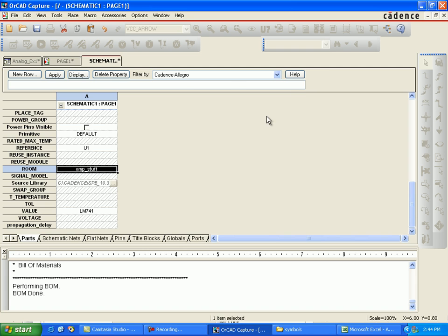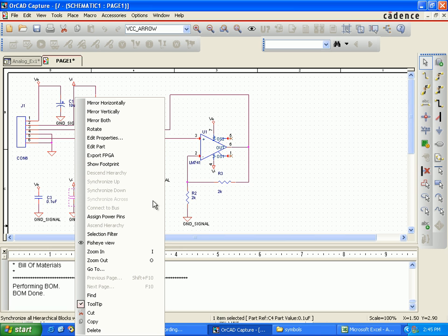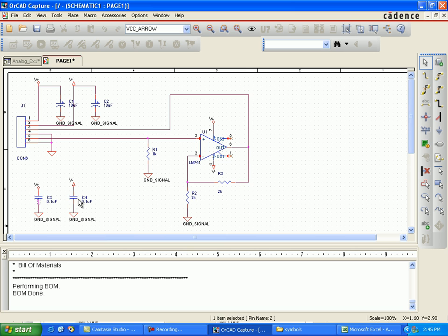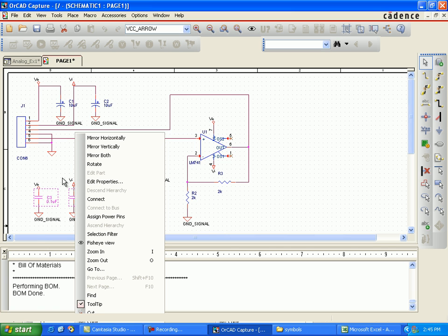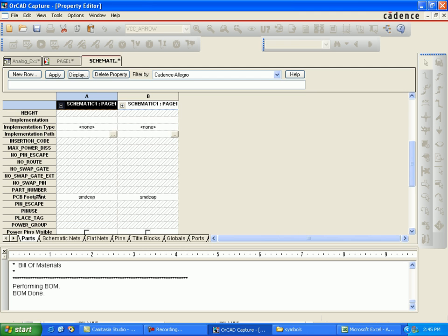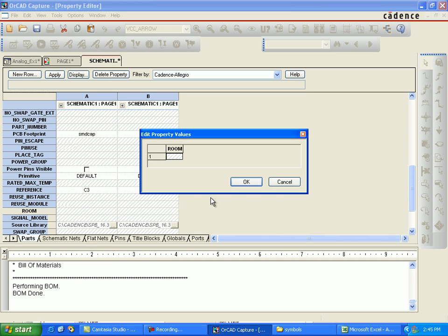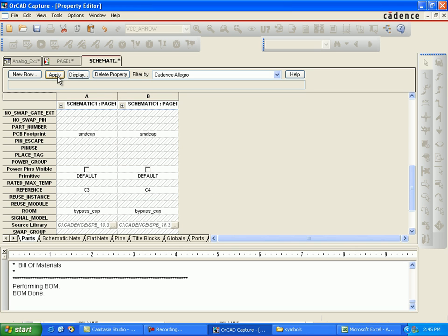So all the amplifier stuff on the PCB will be grouped together, because when your design gets complex ahead, it is better in the beginning to make all those rooms before it becomes too complex. These are all the bypass capacitors.